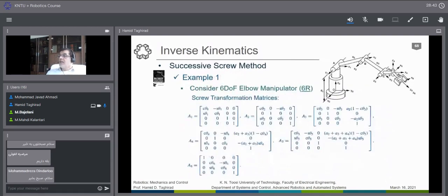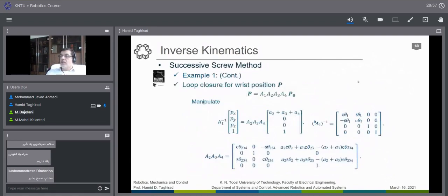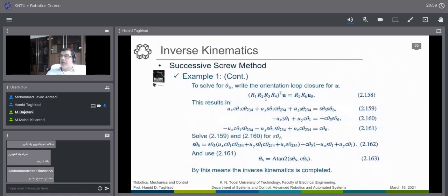Let's go through this. When we say U0 is this direction and this direction, the orientation of the end effector will also change. So we can use either U or W. Here we use U, which gives us the simpler relation. And since we have theta 1 to theta 4 all given, instead of bringing the variables, we can put everything in here.